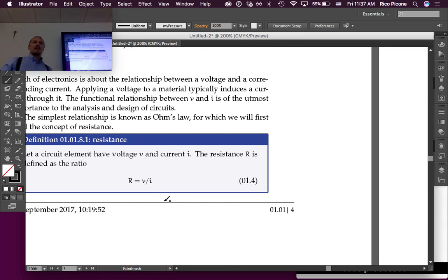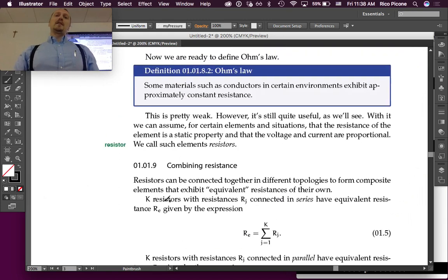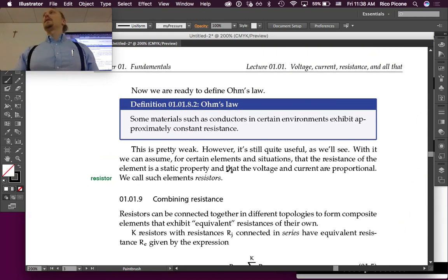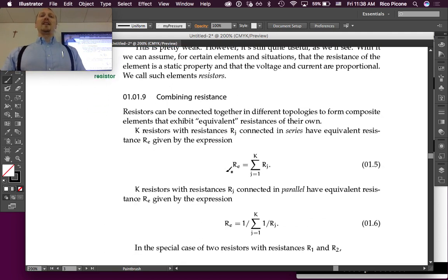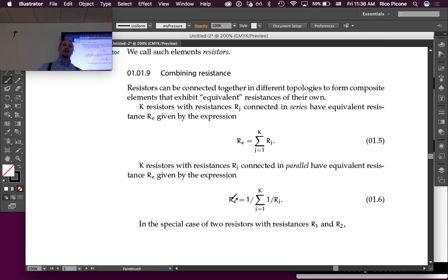And even the resistors that you buy that are called resistors don't behave as perfect resistors. For instance, when they heat up, their resistance changes. Sucks, because what a resistor does is literally generate heat. So it happens a lot that the resistance changes. So approximately, it's not that bad to consider them to be constant.